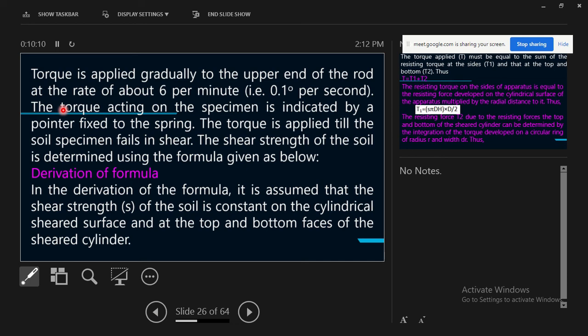The speed at which you load the material determines this. You can get what is called an apparent reading of the strength, which is not correct. In theory, a high strain rate will give you a false high strength. That's why you need to control it. There is a strain rate within which you get the correct strength, but if you use an unreasonably high loading rate, you will get an unreasonably high strength as well. This is why we have to give these restrictions.